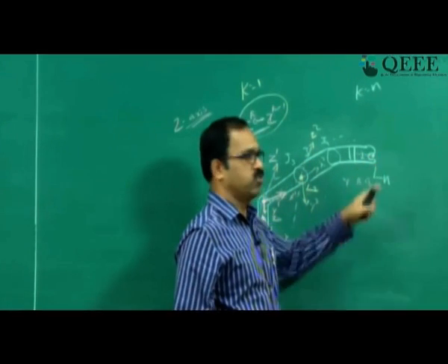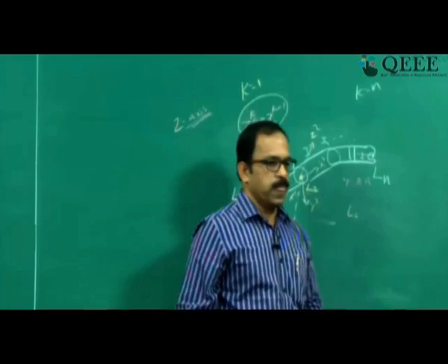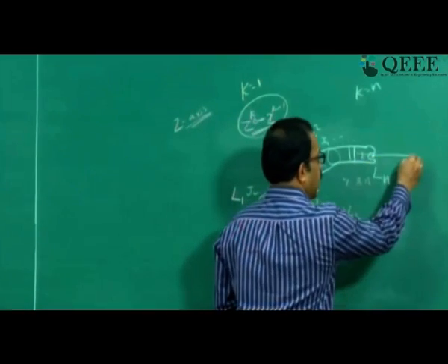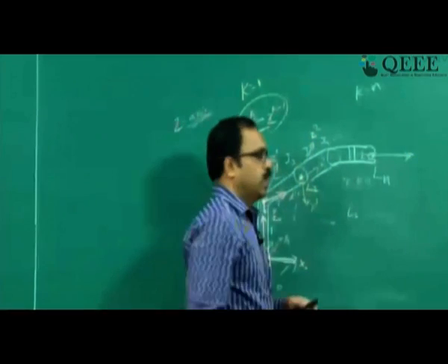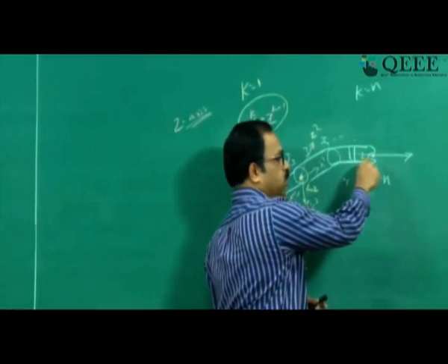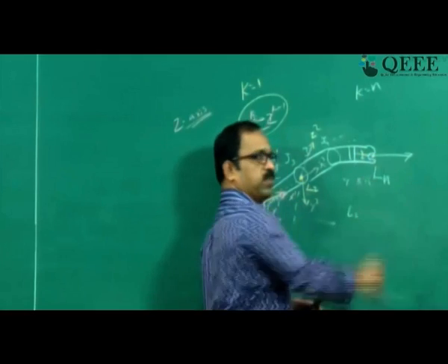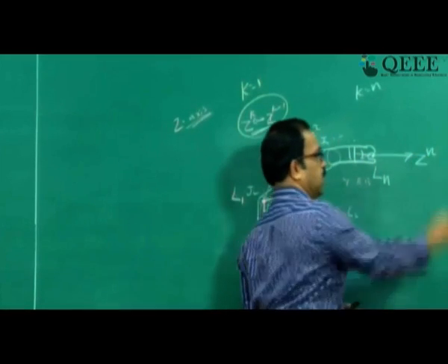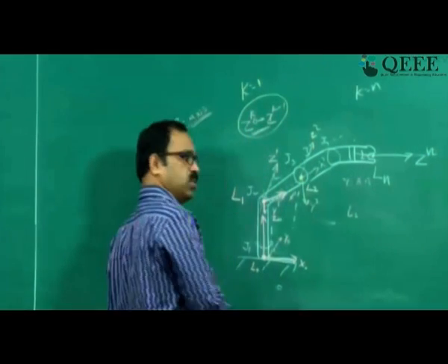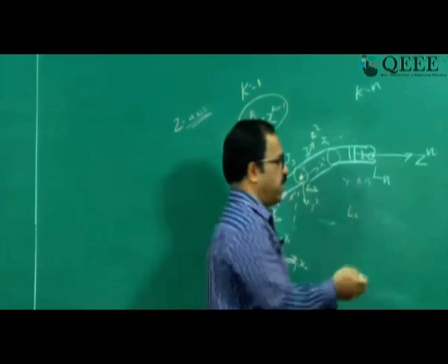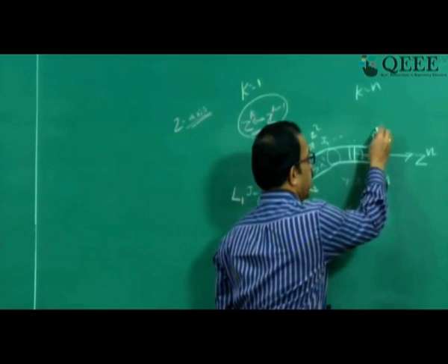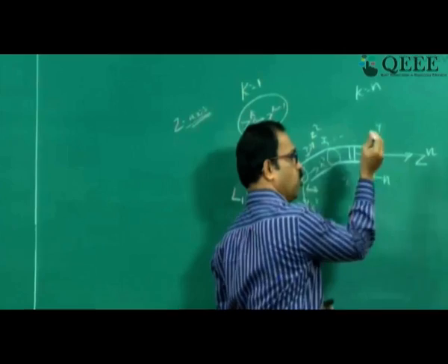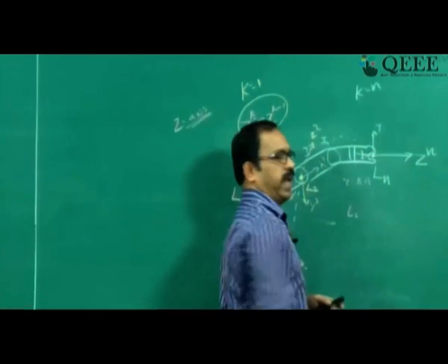If you have 6 degrees of freedom, this will be L6, and assign the coordinate frame like that. This is the approach vector, along the roll axis of this tip, the last joint. You assign Zn, that is the last Z axis, and the open-close direction you give the Y, and then the normal to this will be the X axis.